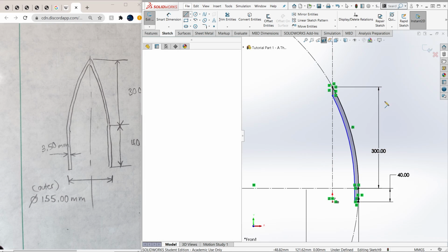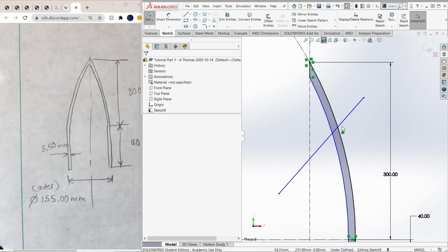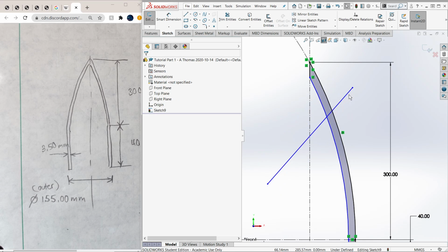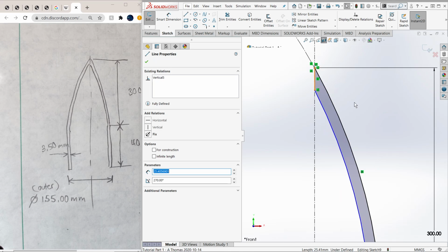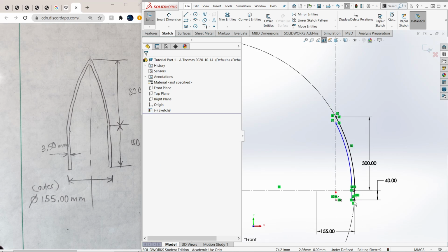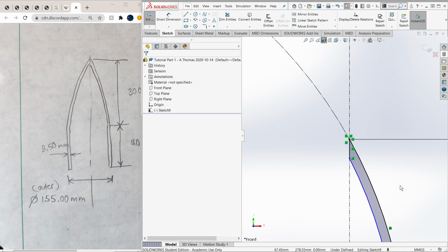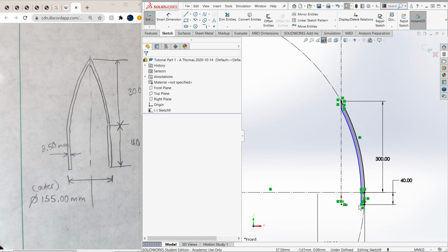If I were to just stick a line through this randomly, this is not a closed surface, because it is a line that will be read by the software, but it doesn't make a shape that it can revolve or extrude. It's just a random line. So you need to have closed curves. So that's open. If I do that, now it's closed.